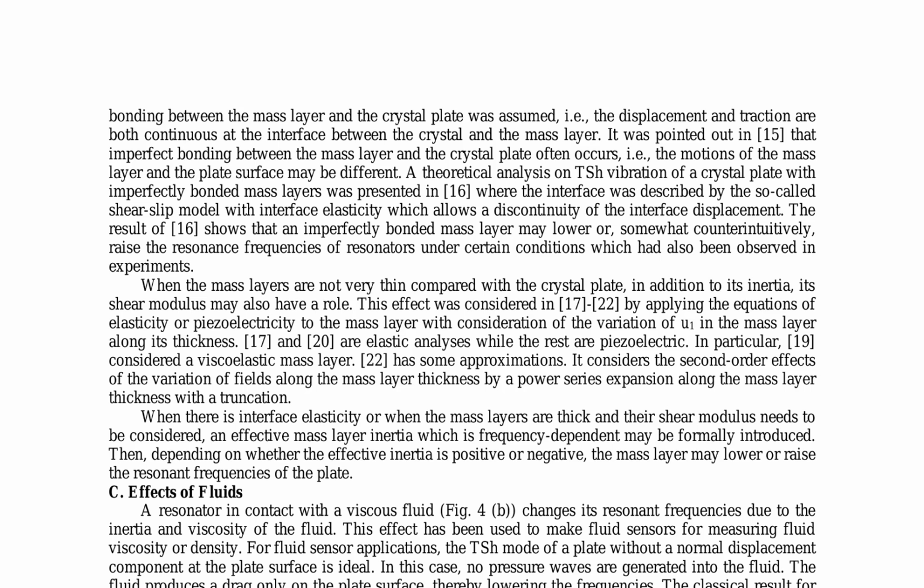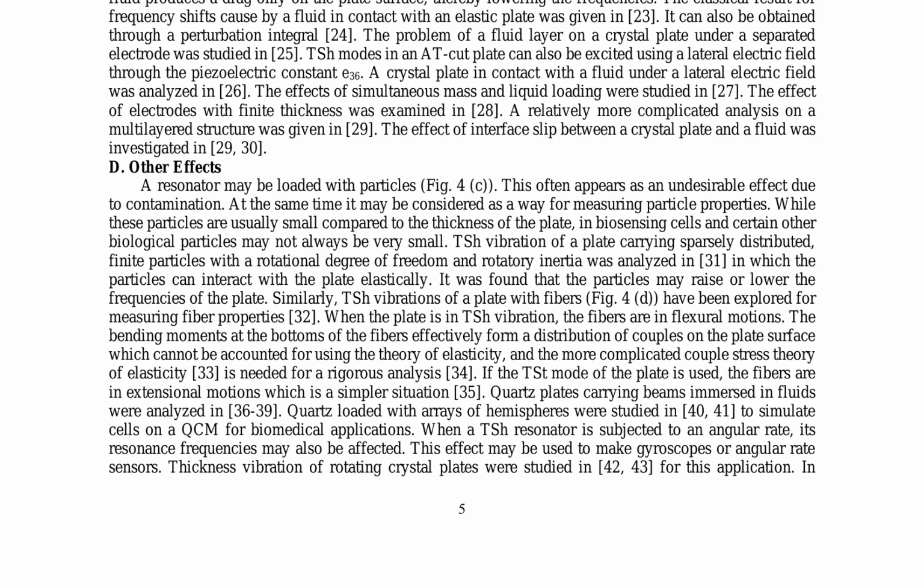An effective mass layer inertia, which is frequency dependent, can be introduced to account for interface elasticity or thick mass layers. The effects of fluids on TSH vibrations are also examined, including the use of fluid sensors to measure fluid viscosity or density. The classical result for frequency shifts caused by a fluid in contact with an elastic plate is presented, along with subsequent studies on fluid layers on crystal plates, electrodes with finite thickness, and multilayered structures.